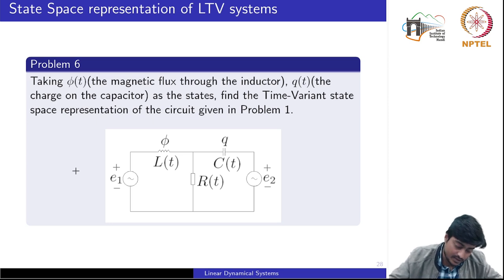Now we have chosen other state variables, and we want to see whether with respect to those we can again obtain a similar kind of state space representation. We also know at the outset that if the states are different, and since the system is already known to us, we would have some representation, but in that case the A and B matrices would be entirely different.